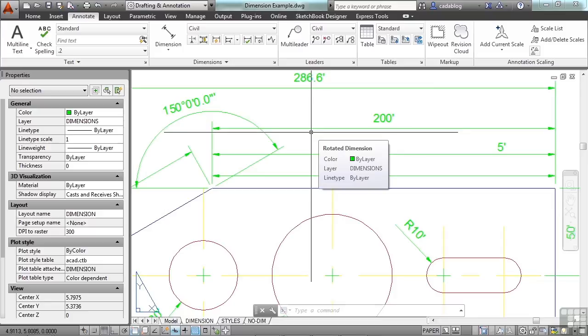The setting of 2 sets your dimensions to the insertion points based on the model space objects that you select. It does several things for you. Most importantly, it measures the true distance that's involved, and it means that you can make one dimension style for the entire file regardless of the scales used. Before we had the setting of 2, we just had 0 and 1. We had to make tons of styles, one for each scale that we could possibly use in our drawing. This got redundant and difficult to manage.